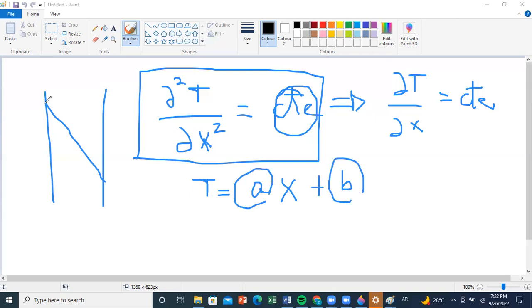I tell you T surface 1 is equal to this value and T surface 2 is equal to this value. Then you plug in to get A and B. Or, second approach, I can give you, as I did in this problem, T infinity 1, T infinity 2, and the convective coefficient. And we'll remember now in this problem how to proceed to deduce the value of TS1 and TS2.